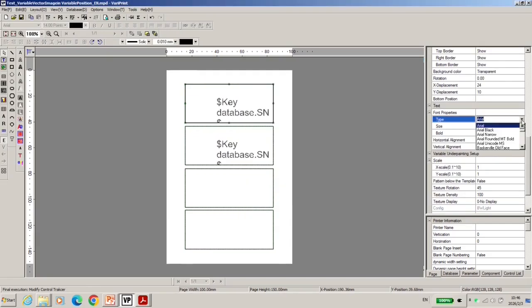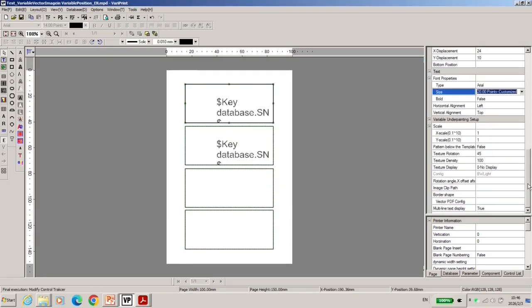Then you choose font type and the font size. Then important is here, rotate angle. We support these different rotate angles. How to choose depends on your target file printing effect. Then you choose the density. That means the LPI. You must use this LPI matching with the lenticular film in the future. I choose 100 because I found 100 is easy to read the watermark.